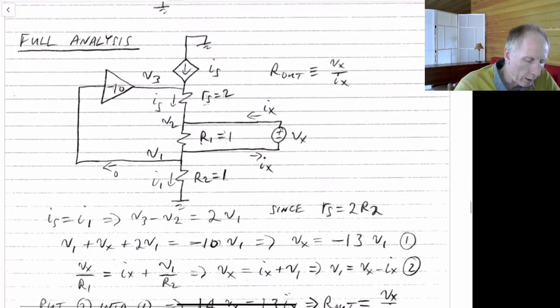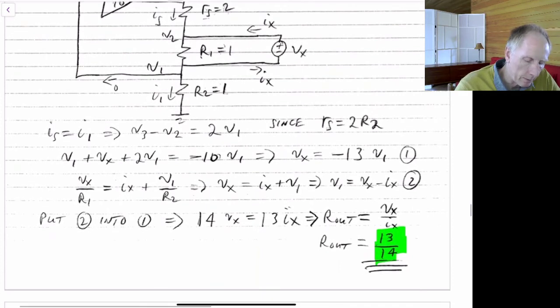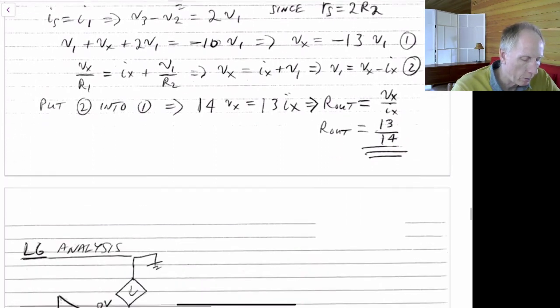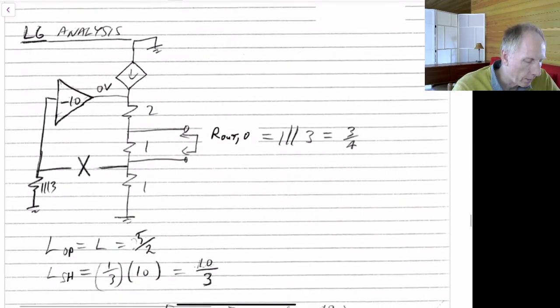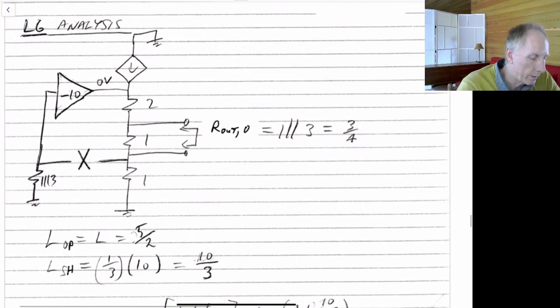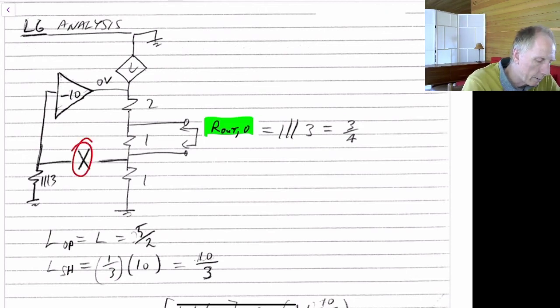And again, you can walk through all these equations here. We just want to see that we're going to get the exact same answer when we do loop gain analysis. So in this case, this becomes our small signal model with the T model in for the transistor. We want to find the port impedance first when the loop is broken.